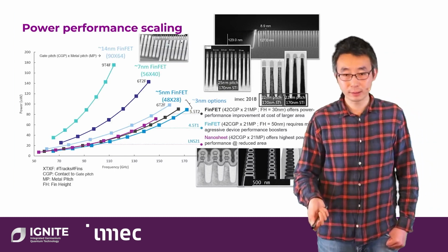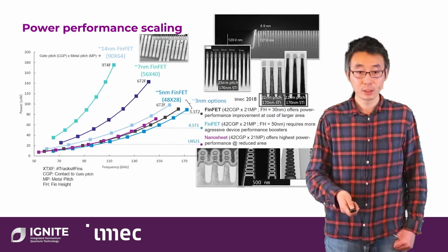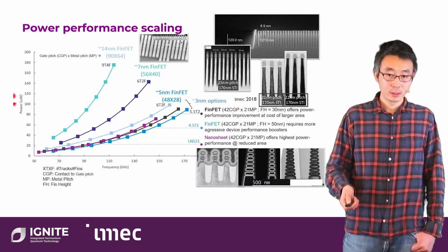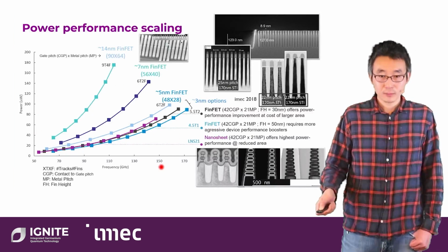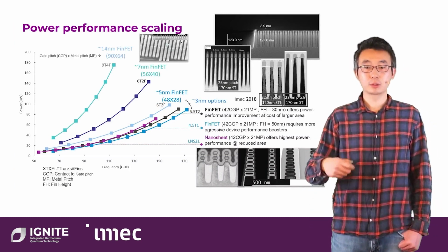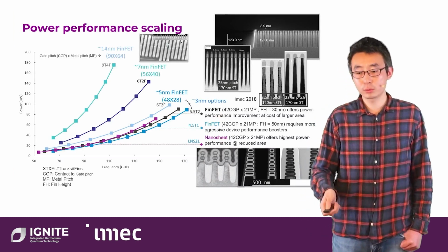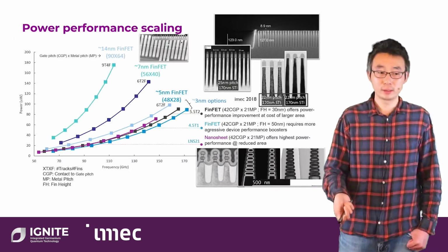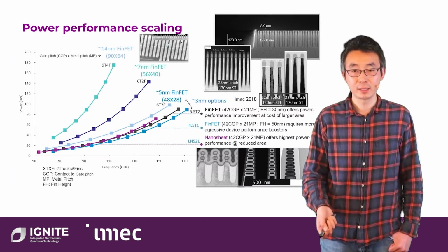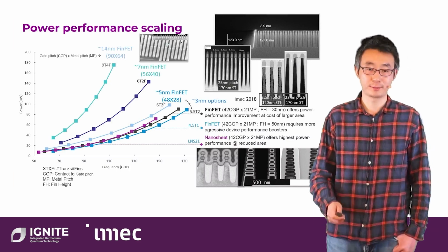And then to characterize the device performance, it's worth looking into the frequency or the performance on the x-axis versus the power on the right axis. Crucially, people expect we operate in this region. So to really go in there, we need to have narrow fins, taller fins, and for better control, we need to go to gate-all-around. But when we go to gate-all-around, that's in the nanowire, then the area is small. So that's something called nanosheet. You can also think of or envision it as an elongated nanowire. So you can also maintain high current flow through, but also have the gate-all-around structure.